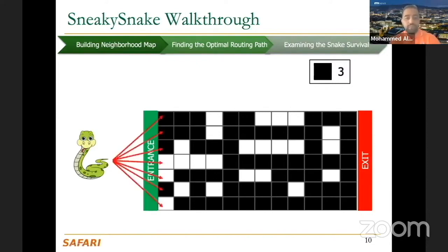So how do we solve it? It's very similar to the single net routing problem. In each row, you detect how many steps you can go further. So you find here 0 steps because you start with an obstacle or a module, then you cannot pass. Here you can move 4 steps forward because your goal is always to go from left to the right. So you want to go as far as possible in each row. That is a greedy choice to get the shortest path. Because if there are no obstacles at all, then you just walk in a single row and that's it.